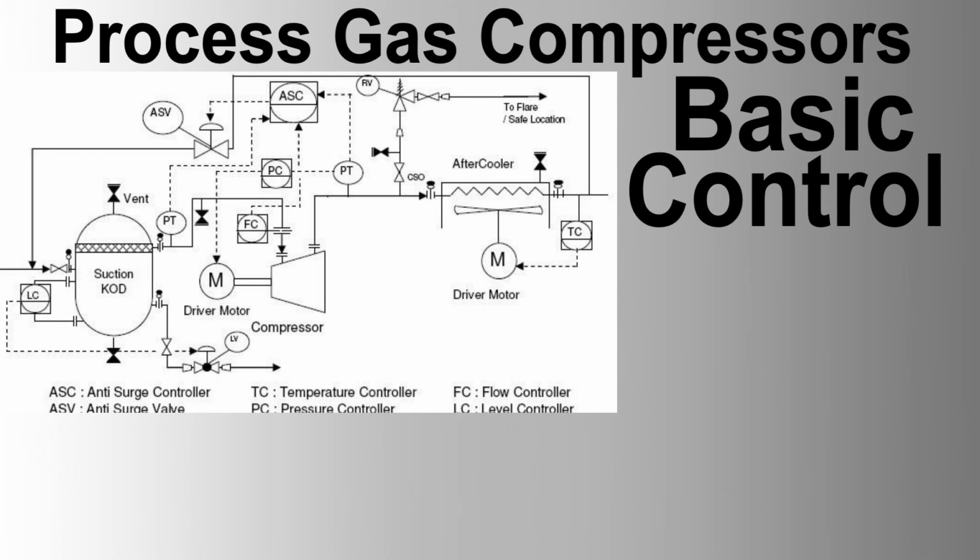B. Anti-surge control. Update the anti-surge control system to incorporate the new compressor. Ensure the anti-surge controllers for all compressors are interconnected and can communicate to prevent simultaneous surge conditions. Add new flow transmitters, FT, pressure transmitters, PT, and recycle valves, RV, for the new compressor.